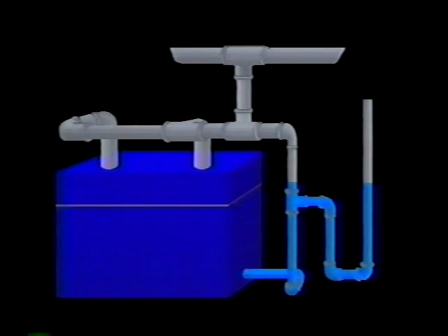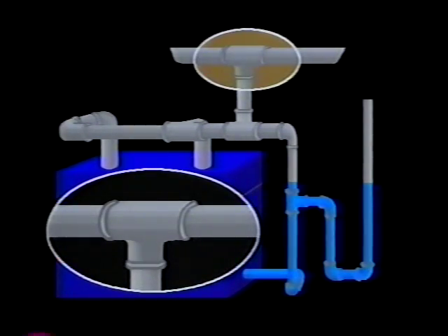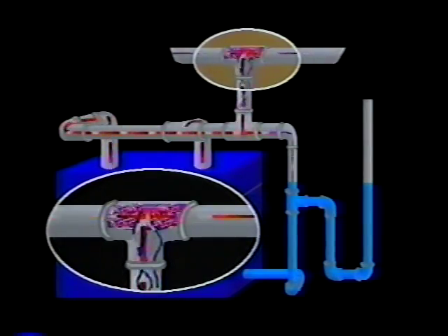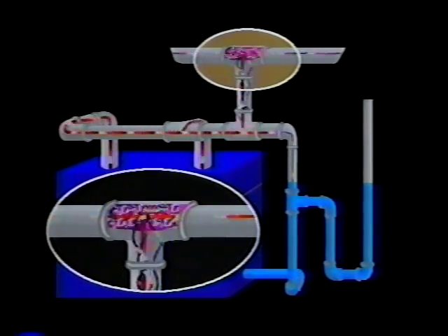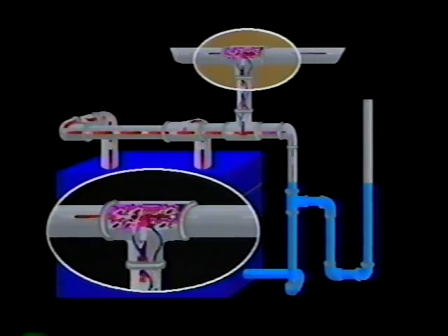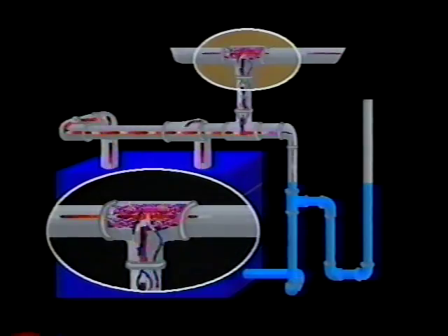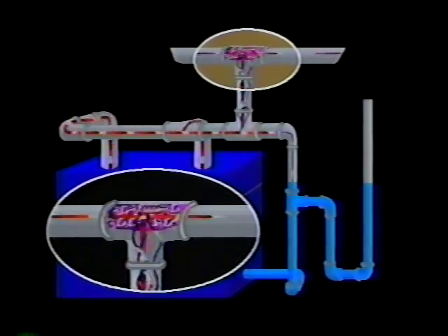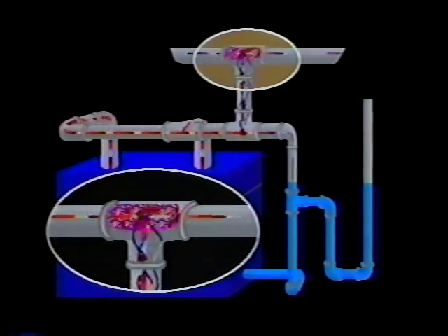This arrangement should never be used. What you are creating here is a bullhead T, where the steam will crash into this T, causing violent disruption of the steam flow called water hammer. Water hammer can be potentially damaging to the piping system and can cause improper steam and condensate flow, along with annoying and undesirable noises in the pipes.